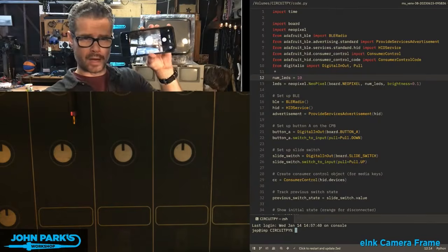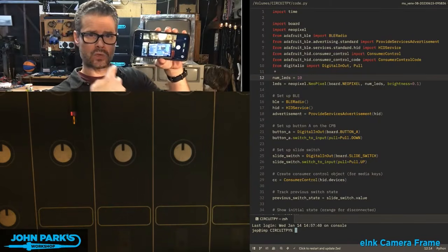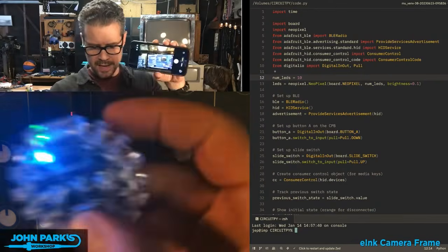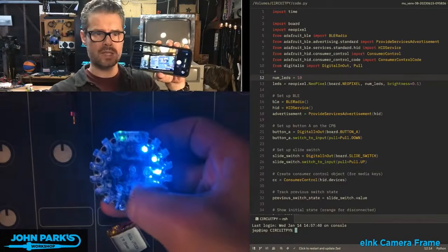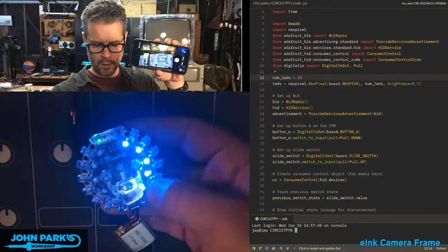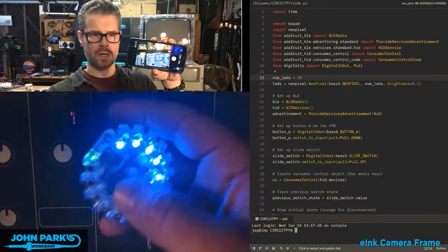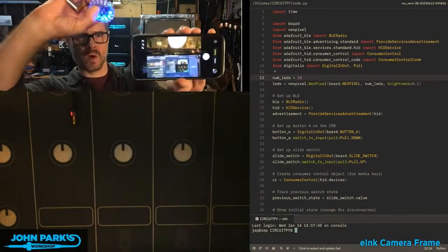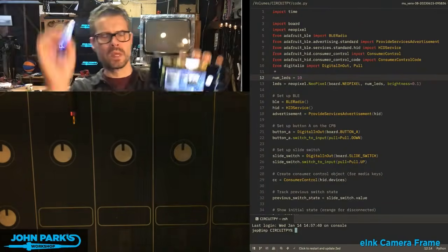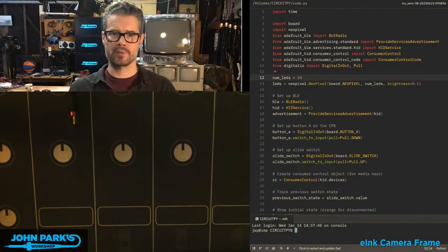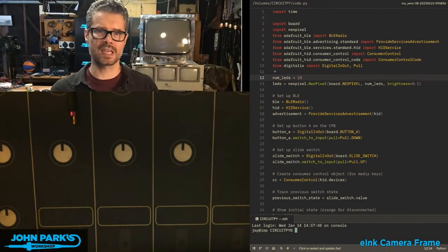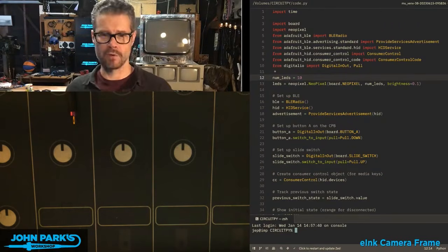However, an intervalometer is something that you can use to take multiple photos on an interval, hence the name. And so what I've done is added a little feature here where when I move the slide switch on the Circuit Playground Bluefruit, it moves into this 5 photo, hence 5 LEDs, intervalometer mode. So I'm going to go ahead and click this and watch, it's going to take 5 photos. Click, click, click, click. So this is great for capturing sports, for capturing motions, movements. You can have this moving, and rather than taking a video, you get a very distinct set of photos.